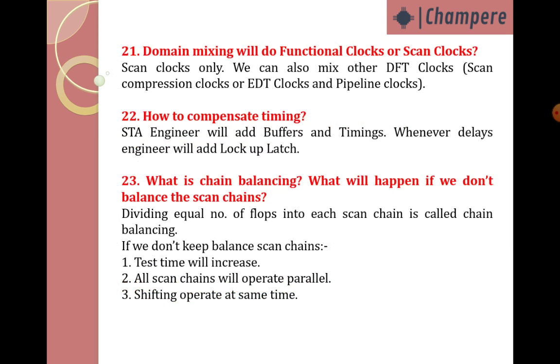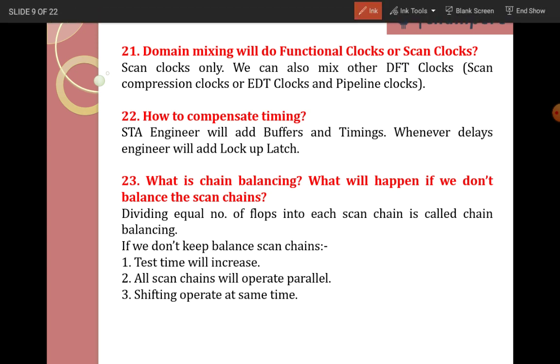And next, domain mixing will be done on functional clocks or scan clocks, very important. Domain mixing means clock mixing. Edge mixing means mixing different edges of flops. Here domain mixing will be done only on scan clocks.